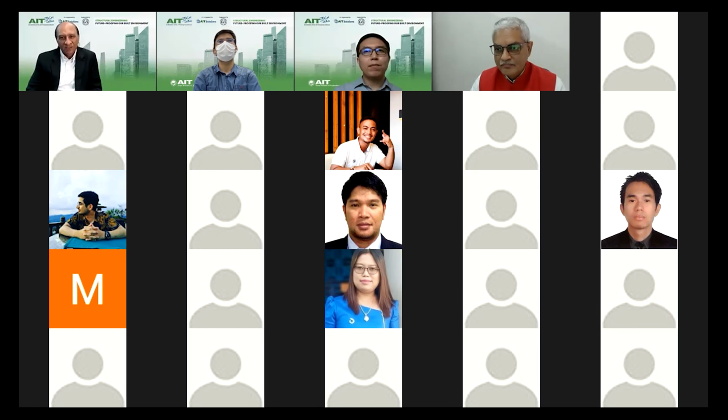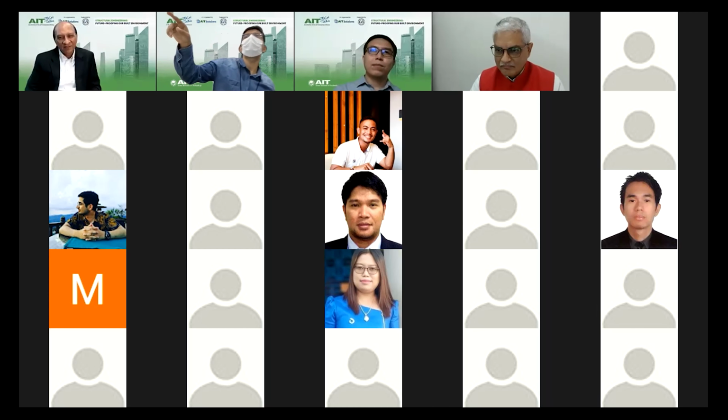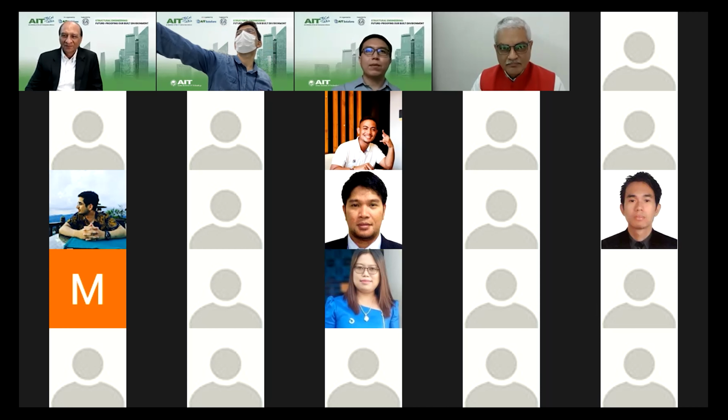I think we will get there soon, where the software should be able to do multiple analyses for the same building with different loads and different factors, and then put things back together. That's something we should be working towards. This whole business of arbitrary stiffness modifiers is a good thing, but it's not really correct. It's not realistic. But this is the best we have at this time, unless we model everything nonlinear.